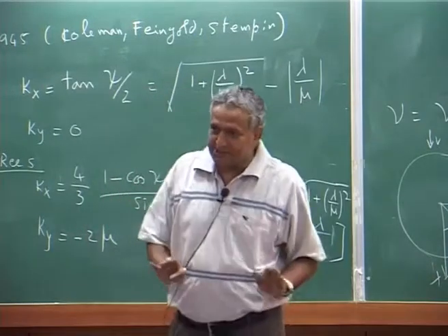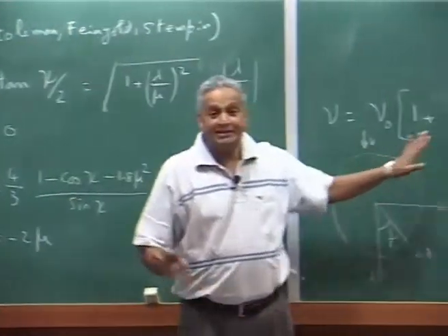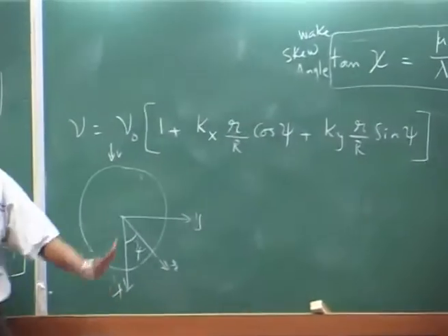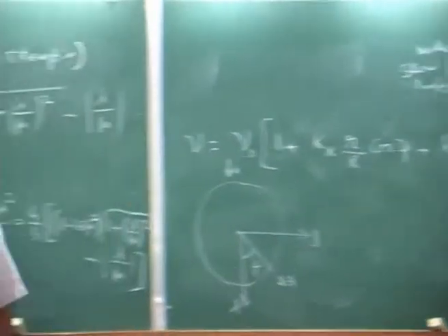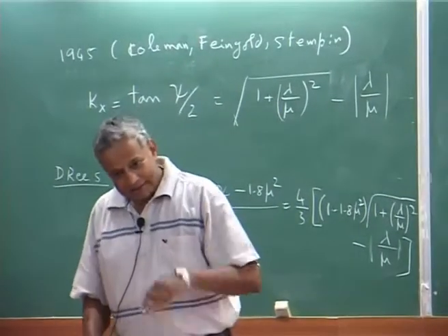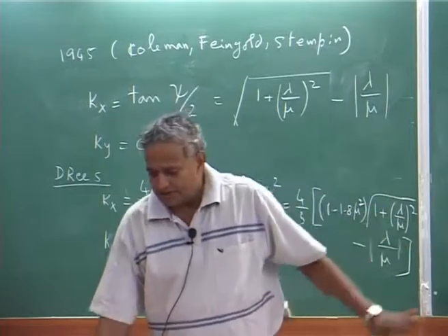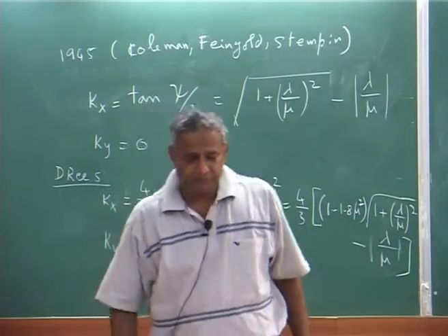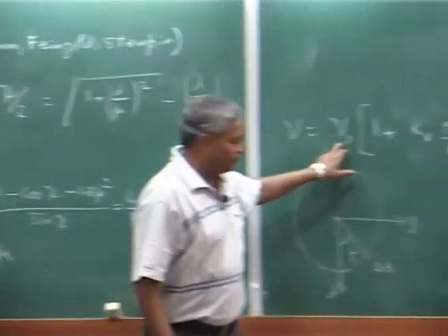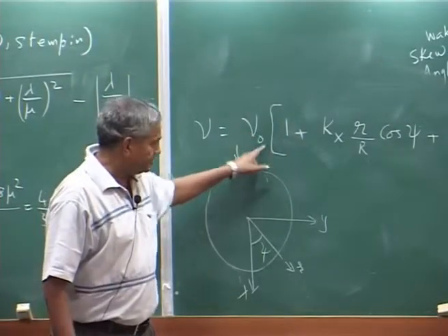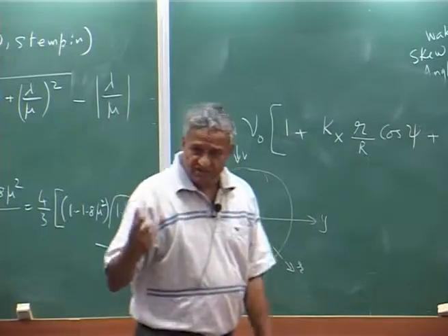Now we got an expression for inflow in forward flight. Good. Let us now go back and actually start. We learned momentum theory. How do we apply it? Because you know that for you to get this nu naught, you need to know CT.